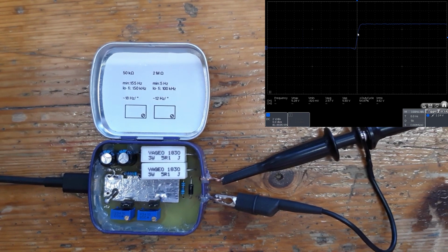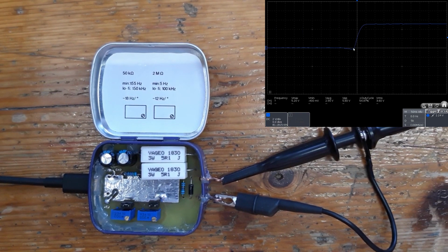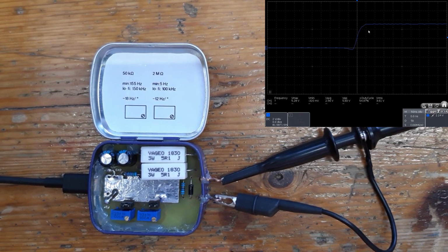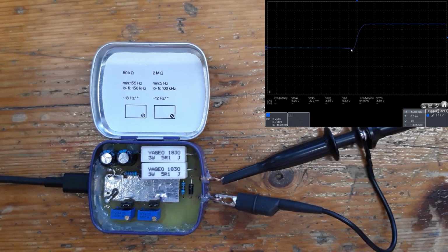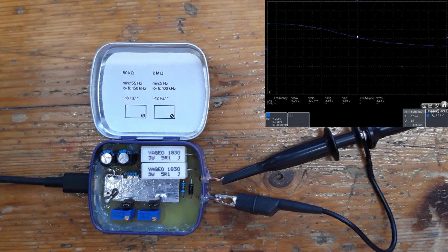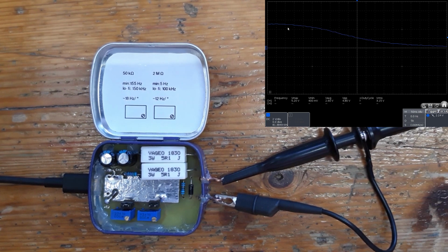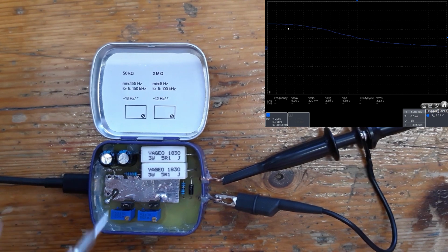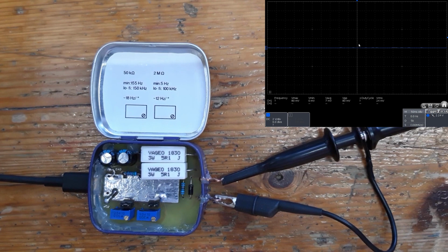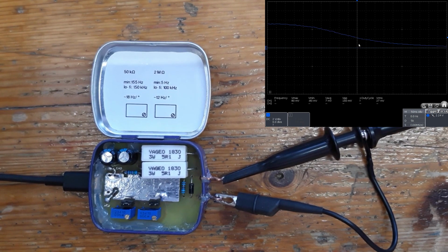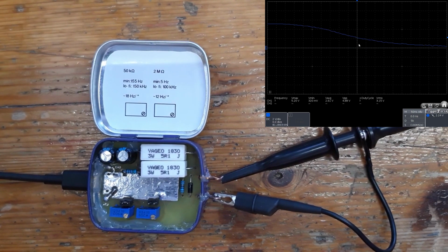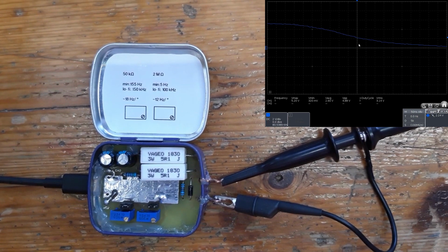Let's zoom in and see the rising edge, and it's pretty clean, as you can see. 100 nanoseconds, not the fastest rise time, but pretty good. And the main culprit is, of course, the falling edge, because of that p-channel MOSFET, and it's so dirty. I want to wash my eyes after seeing that falling edge. But yeah, it's still good enough for the purposes of mine.